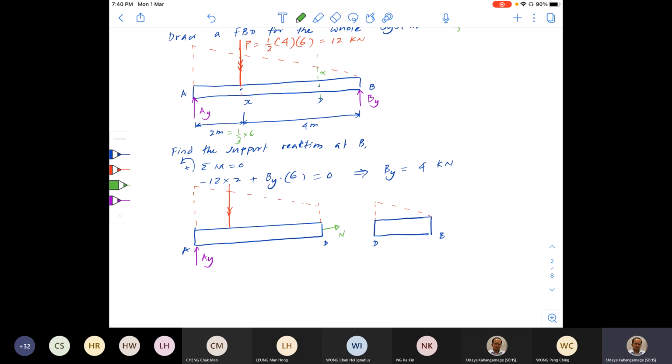And at the point D, therefore ND. Okay. And there can be a shear force, which is along the cut surface. So I just mark the shear force in this direction, downwards this way, and mark it as V. The normal notation we use for shear force is V.